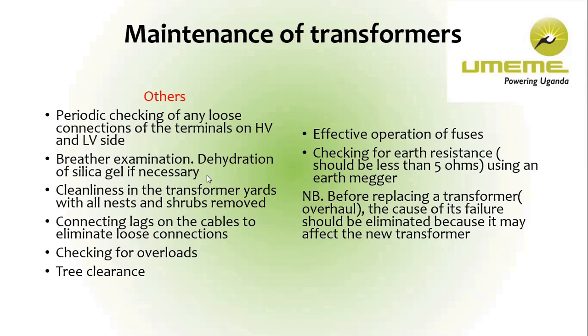Not you putting 100 amperes on red and 0 amperes on blue. You have to make sure that you balance the loads properly. So that is what we call checking for overloads.